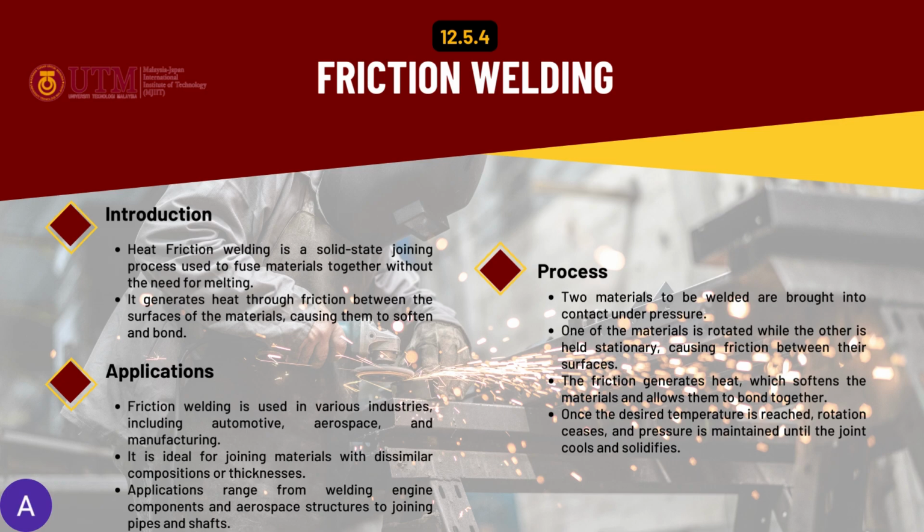The fourth one is friction welding. Friction welding is a solid state joining process used to fuse materials together without the need for melting. It generates heat through friction between the surfaces of the materials, causing them to soften and bond.